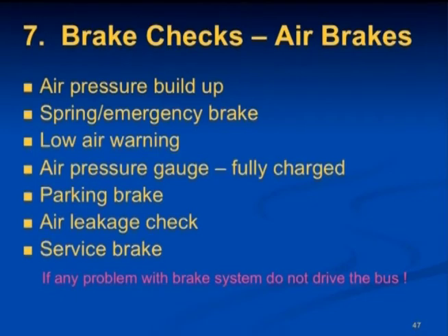Check the air pressure gauge periodically as you're driving. It is important to know how your brakes work and how to check them for safety before beginning your trip. If any problem exists with the brake system, do not drive the bus. Federal and state laws forbid operating an unsafe vehicle.